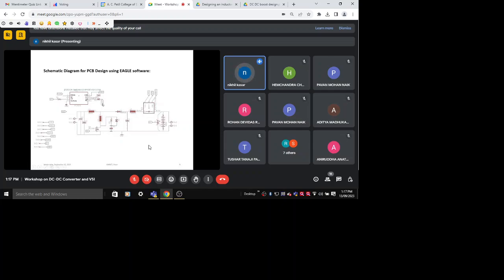Means whatever potential of this main circuit. This is the reference potential, the negative terminal, negative wire, which is running from this input up to the output. This is the reference potential or ground, we can say. See ground here. So if the source of the MOSFET is connected to this reference, we can say it is a low side switch.